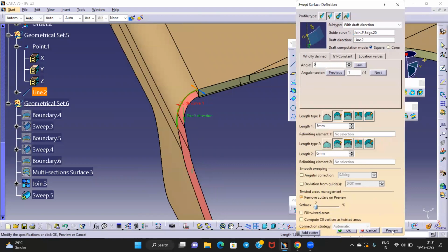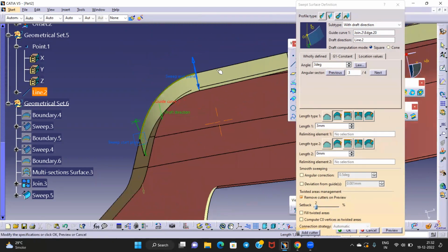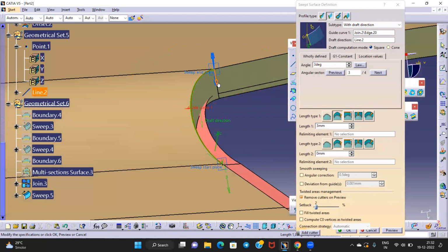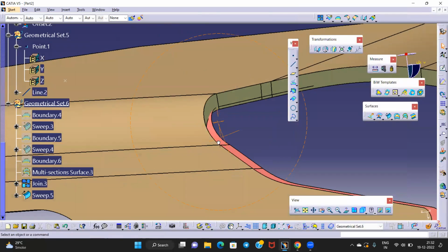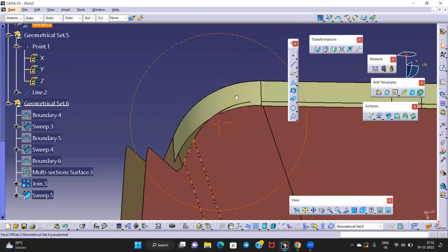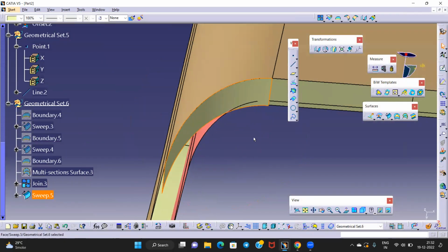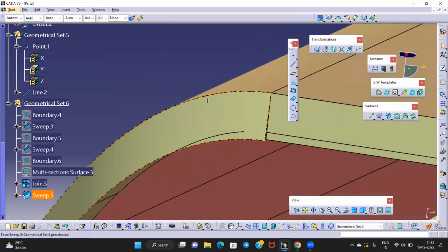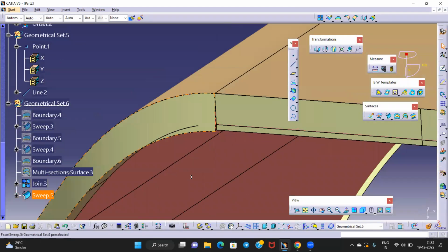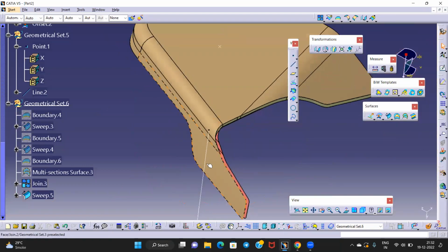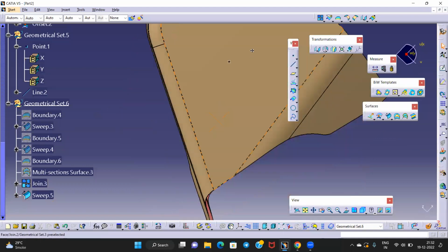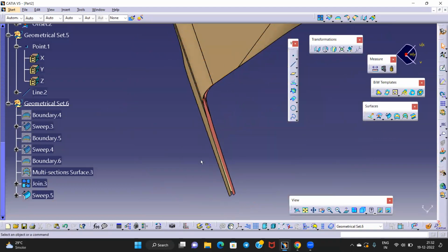Okay, 0 degree below, and we want 3 degree, right? Not 0 degree, 3 degree. Okay, outside arrow we have to select. But it's not coming completely, and here also some gap will come. Let it be, the gap is coming, because the part is like that. This is the visible side. This patch is completely visible, so it is going to clear in the A surface, means the cavity side.